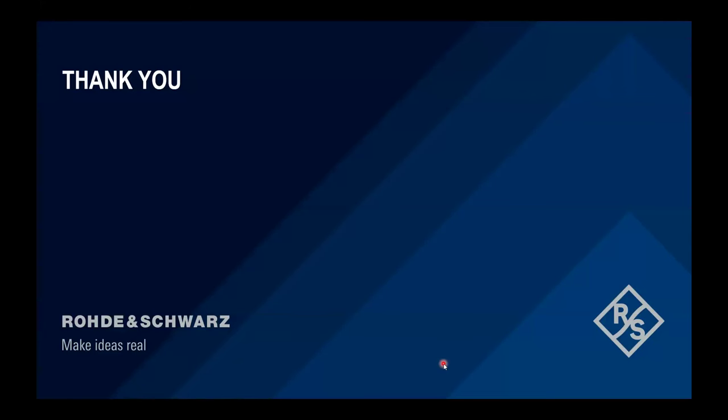So it's not that you're stating, okay, this is a fixed amount of time. It's the other way around. You'll have to ensure under all circumstances that your sequencing leads to a maximum current which does not exceed the capabilities of your source. That's why this is not something I could answer with, it's always 10 microseconds. It strongly depends on your needs, and this has to be ensured in the cycling. It's a cycling definition itself.